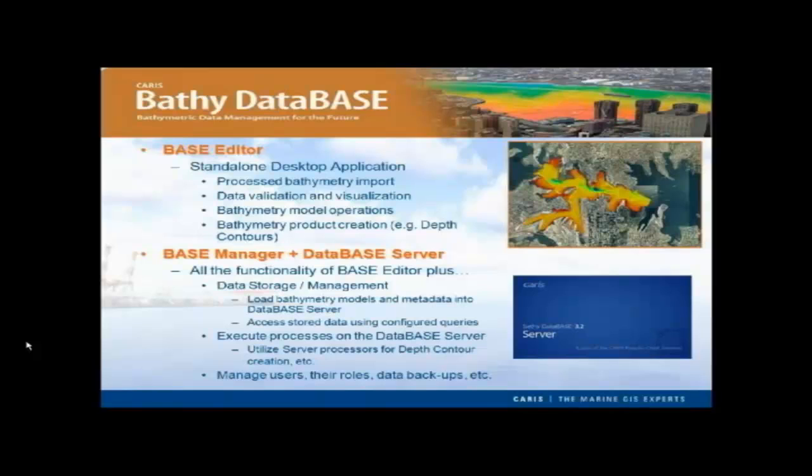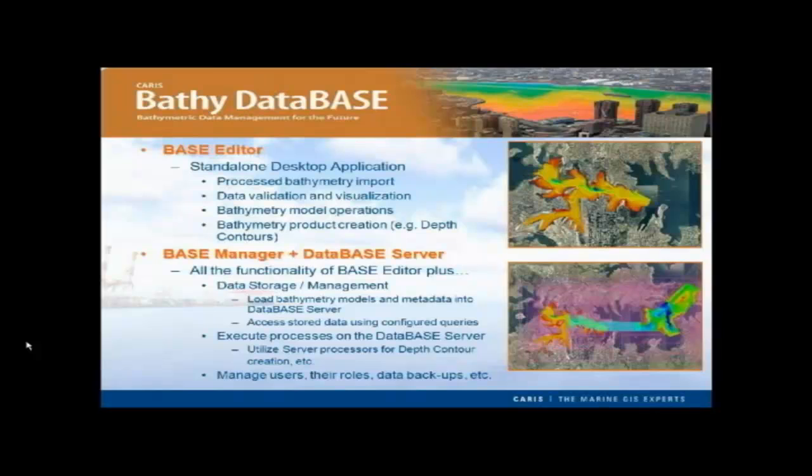It's definitely right, Dan. Now, a lot of the people that have Base Editor might know that we actually have a step up from that, which is Base Manager plus Database Server. This has all the functionality of Base Editor plus the capability for data storage and management. Bathymetry models and metadata can be loaded into the database server and accessed using configured queries. Processes can be executed on the server, allowing users to utilize all the processing power of the server to combine surfaces and anything else that doesn't actually change an existing layer, such as extracting stuff and also creating contours and soundings. There are also admin tools to manage users and roles and database backups.